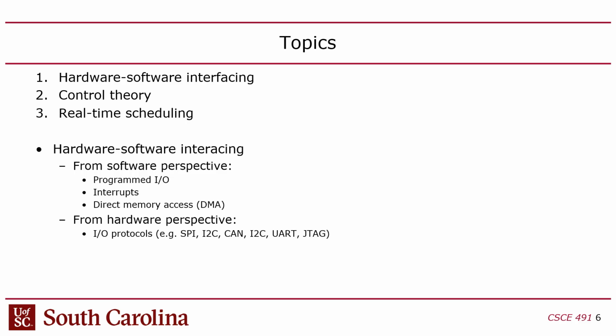So it doesn't matter if you buy an Intel motherboard or you buy an embedded system like the one that we use. You have a repertoire of these address ranges, and the only way to get those is from the user guide, and you can't change them, you're stuck with them. And when you boot Linux up, Linux becomes aware of these address ranges through something called a device tree, which is a separate file that's read when the kernel comes up. To boot Linux, you need 2 files. You need a kernel and a device tree file. Those special addresses are inside that device tree file, right?